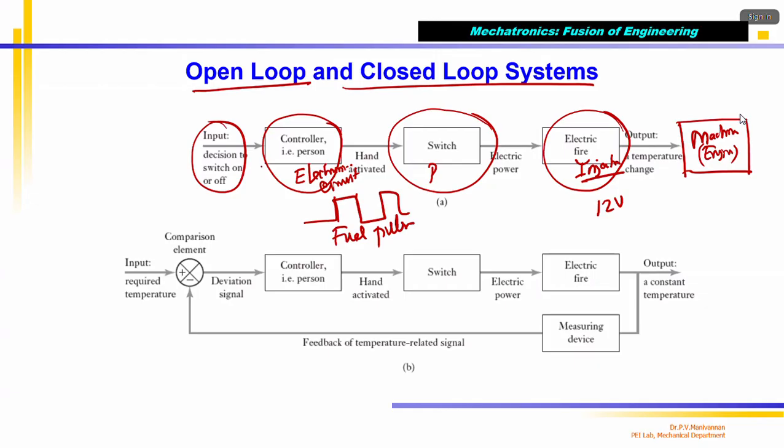When you press the accelerator pedal, correct, you are asking the controller to generate pulse width modulation, which is given to the power amplifier. The power amplifier in turn is connected to the injector, because the ECU develops 0 to 5 volt pulses only. Most electronic circuits work with that if it is a digital circuit. A digital controller will generate 0 volts or 5 volts only, no in-between voltage. They call it binary level, that means two levels, 0 volts or 5 volts, because the computer generates zeros and ones, which we call binary numbers.